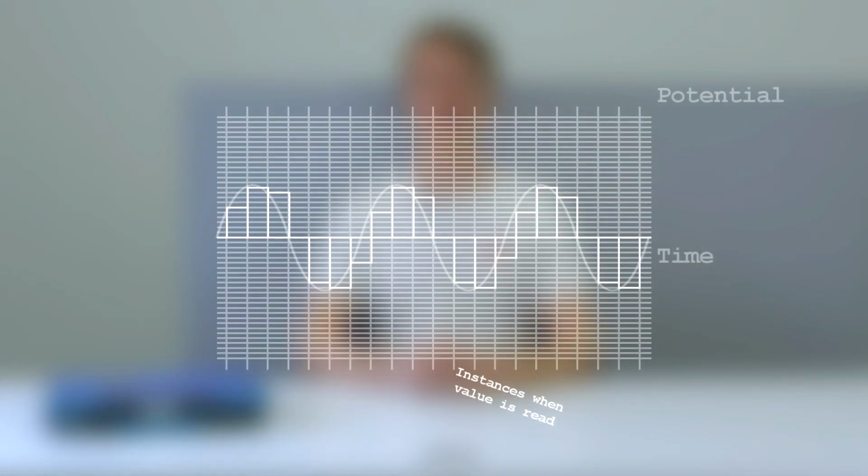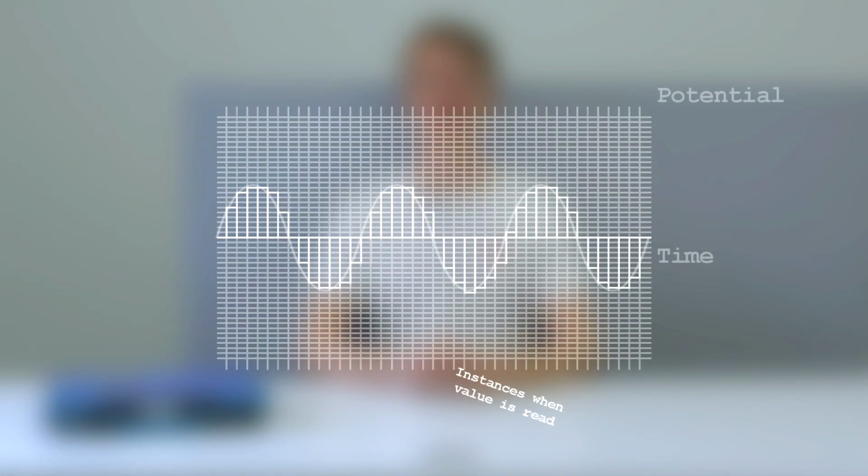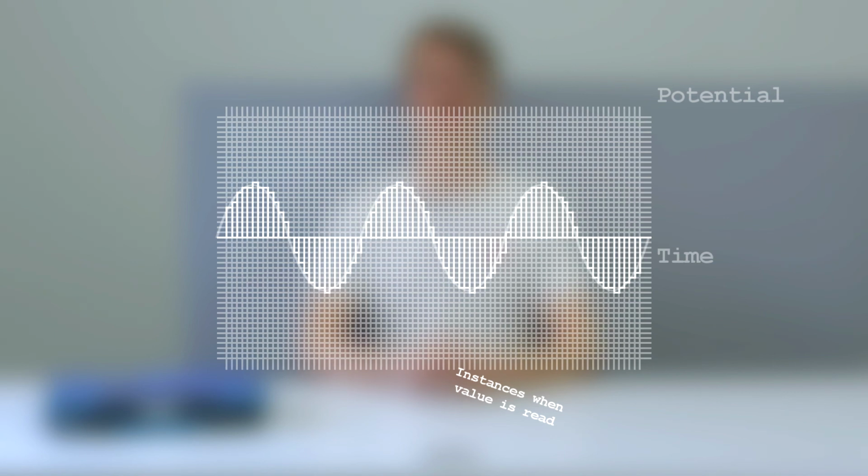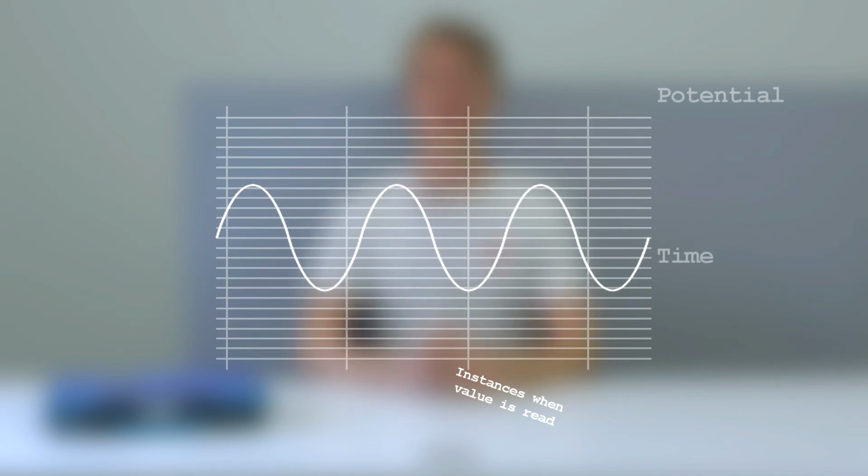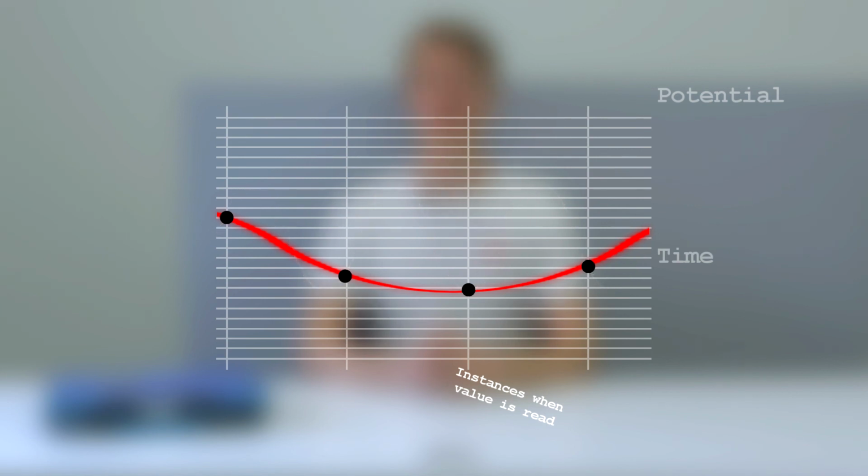To capture the frequency and form of the signal being measured, we need to have a sufficiently high sampling rate. According to Nyquist's theorem, the sampling rate has to be more than 2 times higher than the highest frequency of the measured signal. If the sampling rate is too low, aliasing will occur. This phenomenon is when the measured signal does not match the real signal, even if it appears to be correct. Just from looking at the graph, it's not possible to tell if aliasing has occurred.